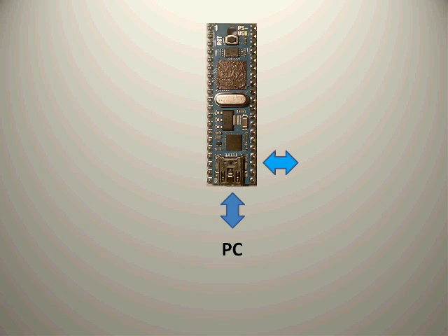There are several other interfaces to the Propeller chip. One interface is a switch interface, bidirectional. A switch interface to electronic switches, for example usable for coil switching. And there's, in the direction into the microcontroller, a signal line for PLL feedback, so that a PLL lock function can be established in real-time operation.